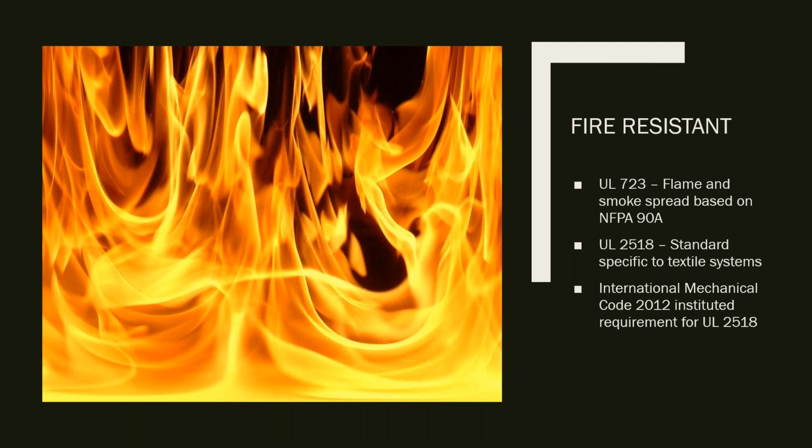So in terms of fire resistance, most people, when they think fabric, think it's a fire hazard, right? Well, fire resistance is a concern for safety as well as code compliance, so there is a misconception there. All modern manufacturers have their materials tested to UL 723 as well as UL 2518, which combined ensure minimal flame and smoke spread. This is based on the NFPA 90A standards, and it keeps its durability over time.